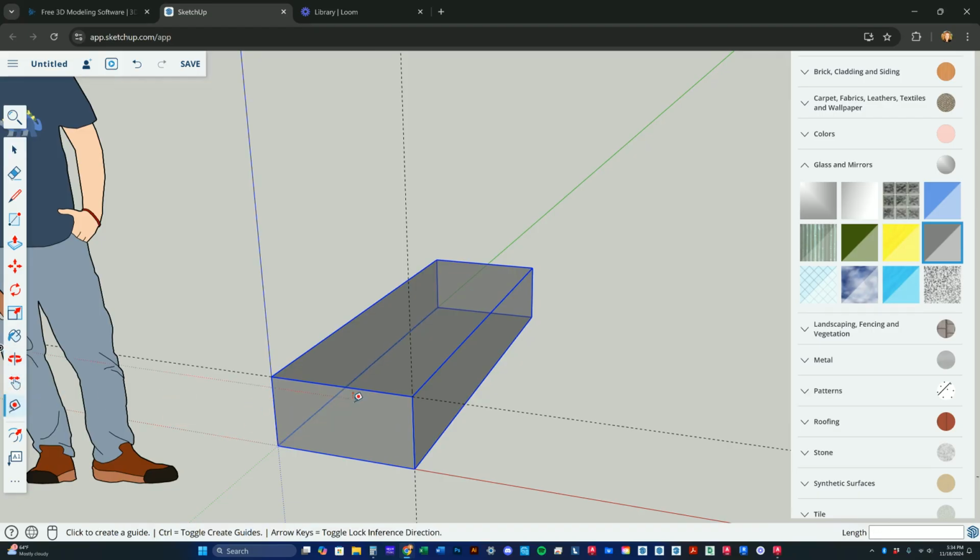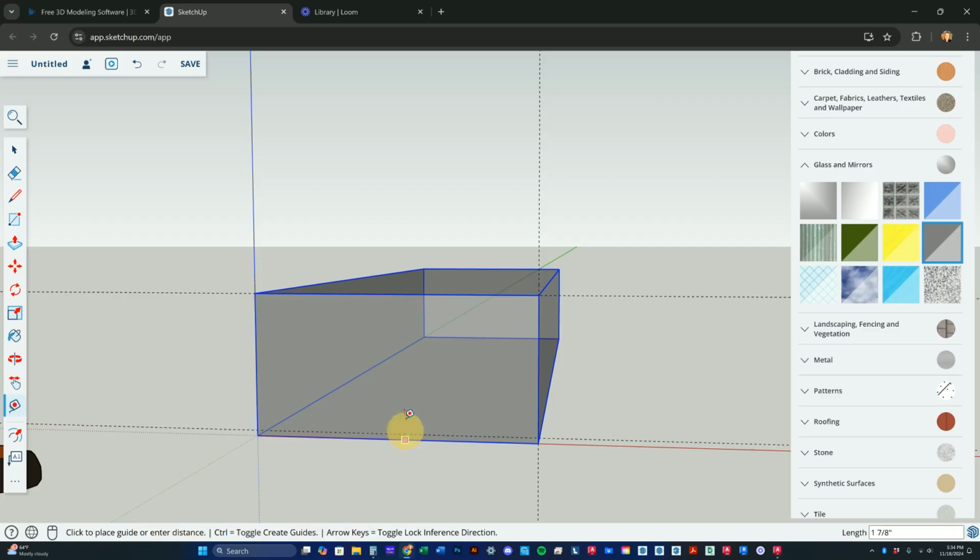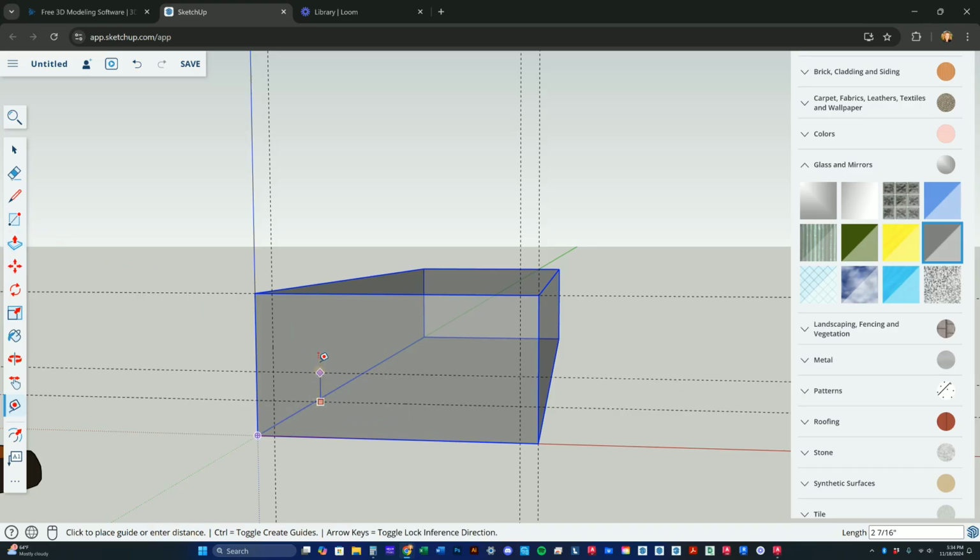And then in order to place our rebar properly, we're going to go 3 inches up from the bottom and 1.5 inches and 1.5 inches. And again, I'm typing those down here in the command line. And then we are going to go, number 4 rebar is 1/2 inch, 4/8 of an inch, 1/2 inch. So we're going to go up 0.25 in order to get to the center of that rebar, and 0.25 and 0.25.